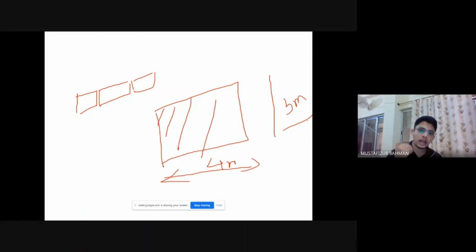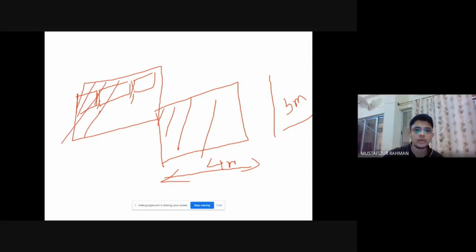And then after that we apply 12 mm of plastering. Therefore we will require some extra material to be applied in the joints so that we have a uniform surface, and over that we will apply our plastering.